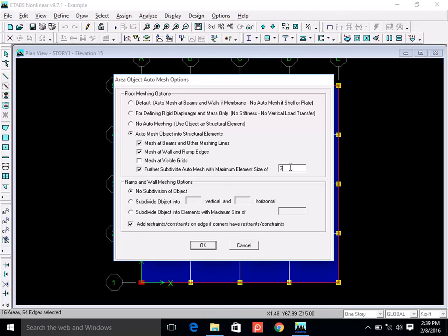So total elements will be 25. There is no recommended size of mesh. If you keep on increasing the mesh size, your accuracy will be better and better because you will be more close to continuous connection. If you have 5 meshes, it means your slab is connected at 6 locations, right? 5 meshes, locations are 6 points it is connected. But in reality, it's continuously connected.